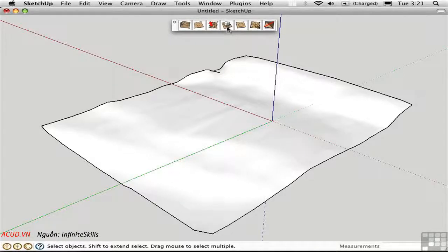The stamp tool is perfect for making foundations, as this icon suggests. What it does is create a geometrical bridge between a flat surface, representing the building footprint, and the organic landform. To see how this works, I'm going to draw the building footprint off to the side. I think I'll make a hexagon that represents this sort of unusual building footprint.